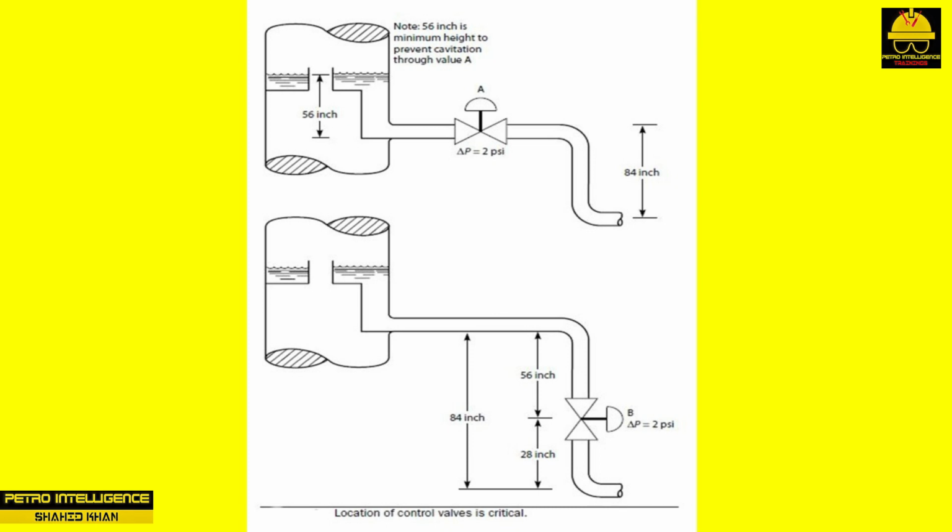Let's assume that the increase in velocity through the draw-off nozzle is small, and hence the nozzle exit loss is zero. The frictional loss through the piping and nozzle is zero. Even after we have made these two unlikely assumptions, the height of hot water in the draw-off sump must still be 56 inches above the center line of the draw-off nozzle.